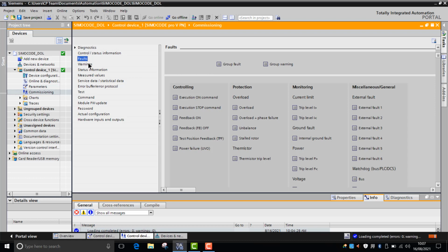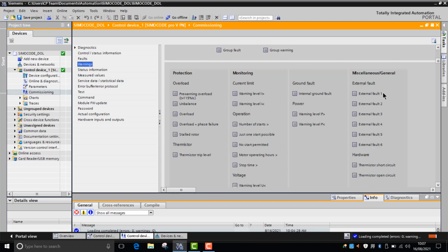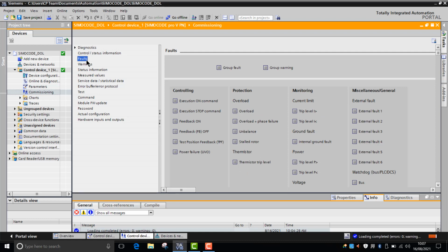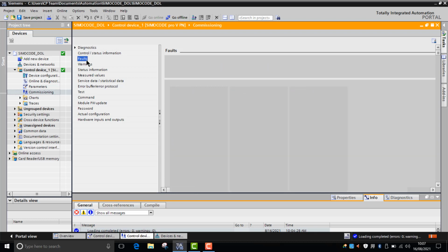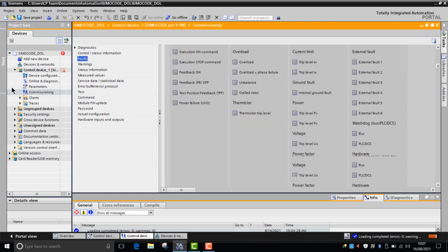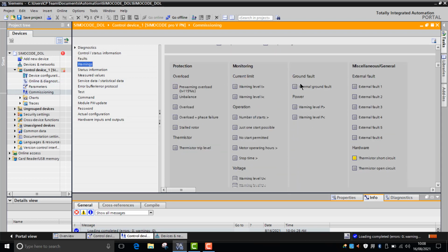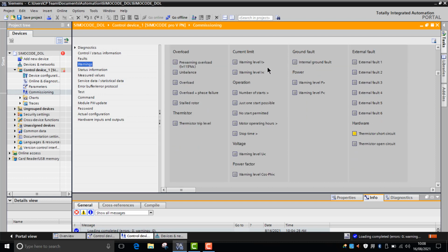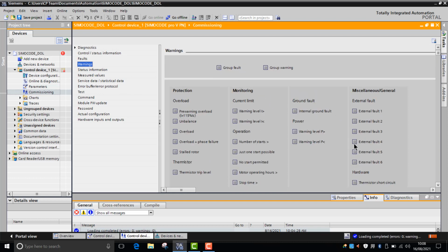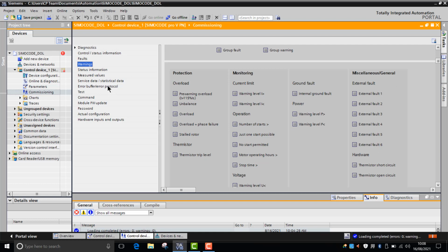So for this example, what we'll do is we'll toggle the thermistor now, and we should be able to see a trip. So let's have a little look at that. So if we turn the thermistor right the way up, as you can see now, the thermistor has gone to trip. So if we turn that right down now and press the test and reset button, that should clear off. As you can see, it has. And as you can see, what I've also done now is I've turned the thermistor pot down, and it's created a short circuit. And as you saw just then, this bar was yellow, so we know that there's a warning coming on when you have a short circuit protection.